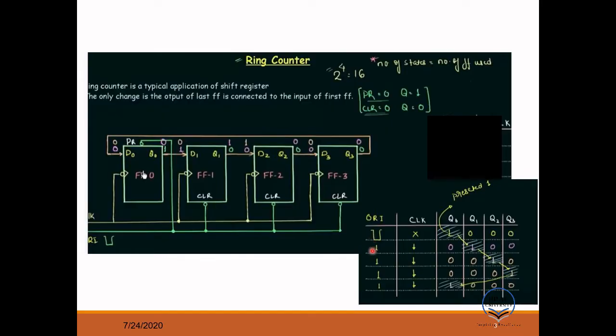Okay, in the next cycle your override gets high. Override high means it got deactivated. That means all the registers will now act as a synchronous counter, or it will be activated through the clock. As it says it's a falling edge clock, it will activate on the falling edge of the clock. So initially, here the green color, this 0 will be coming here, so its input will be 0, right?